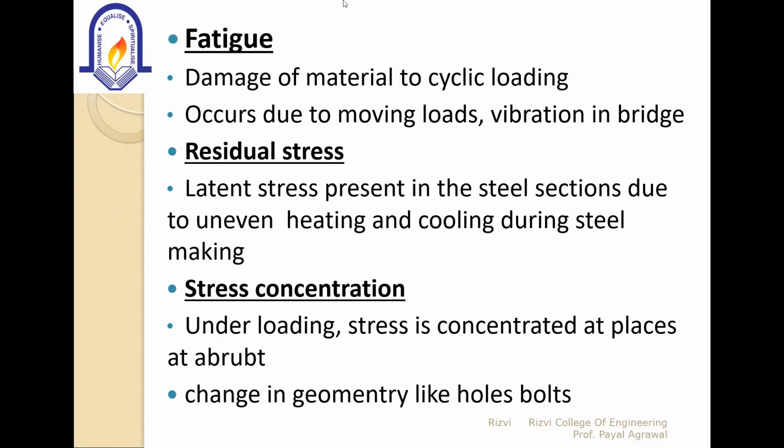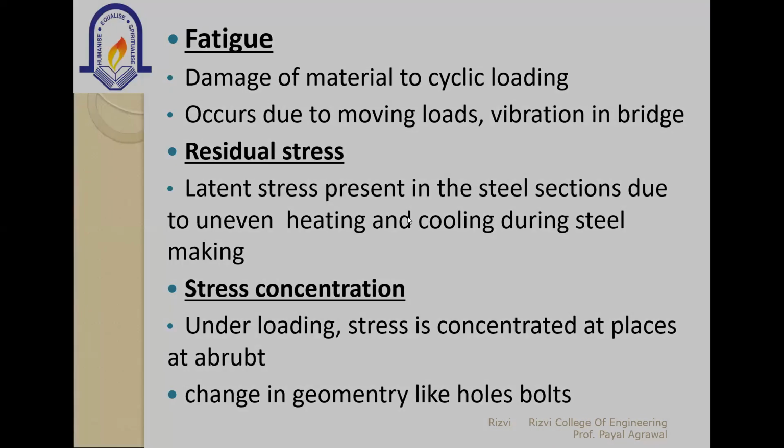And the next important term is your stress concentration. So what do you mean by the stress concentration? So under loading, stress is concentrated at places of abrupt change in geometry like holes, bolts. So that is your stress concentration.